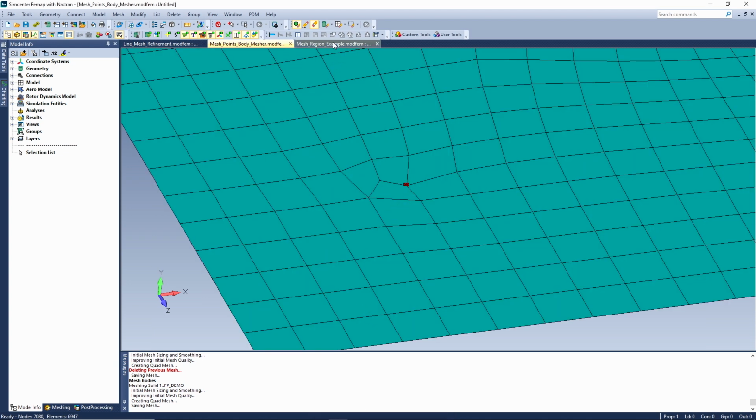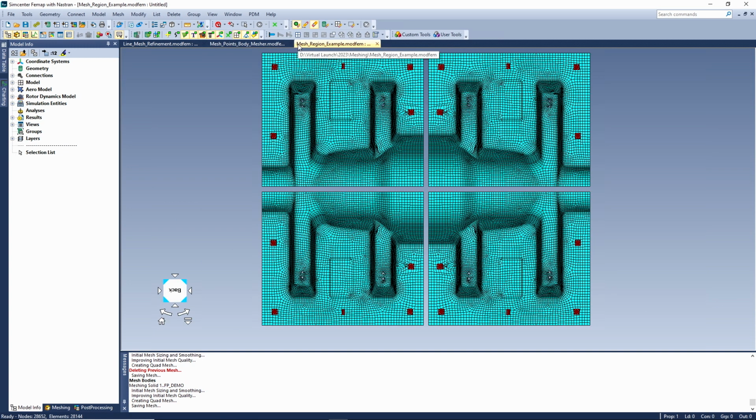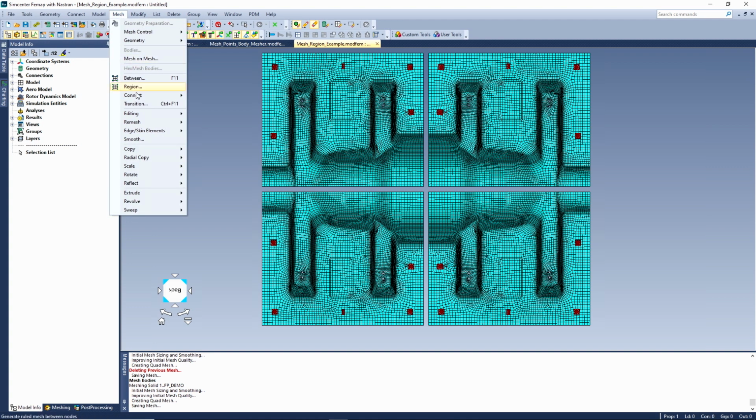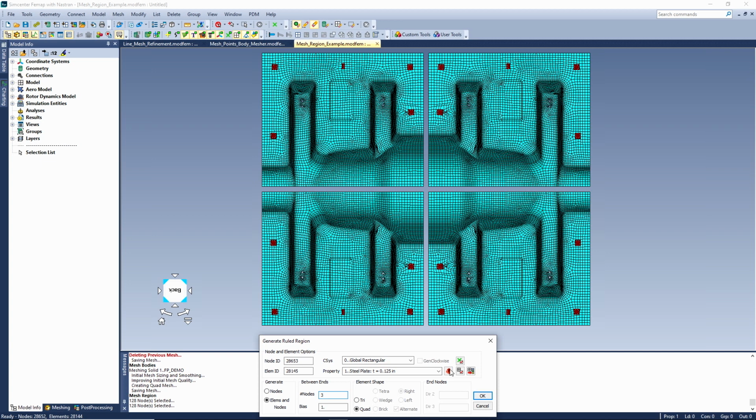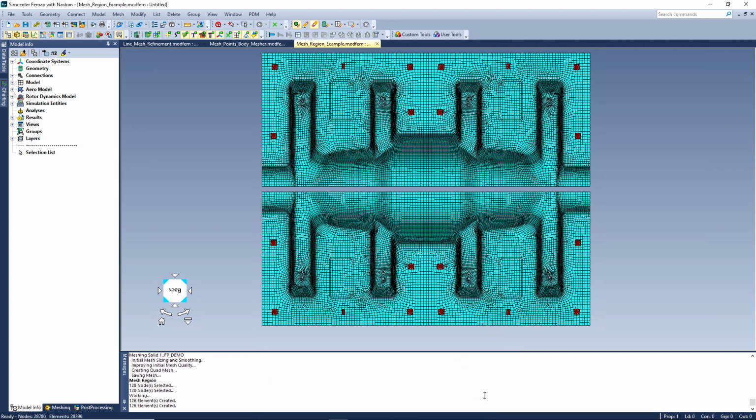have been moved to those mesh hard points. Finally, something we did for 2306 was we really enhanced the mesh region command, a older command within FEMAP. So what we're going to do is we're just going to use mesh region, and I'm just going to select one side of my region. Then I'm just going to select the other side, and in previous versions this was much more difficult because they had to be ordered sequentially, essentially numbered the correct way.